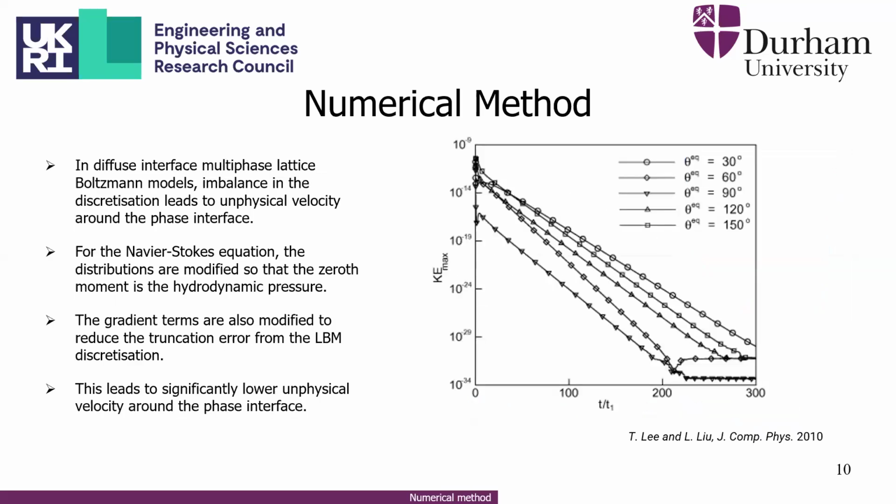Finally, something to mention: one of the reasons we went with the phase field LBM for this evaporation approach is that we've been using this model by Tai-Hun Lee, which reduces the spurious velocities to machine precision. This is showing the kinetic energy, and you get spurious velocities falling with time until they basically flatten out. This helps to improve the stability of the simulations and the accuracy of results. This model can also handle high density and viscosity ratios.